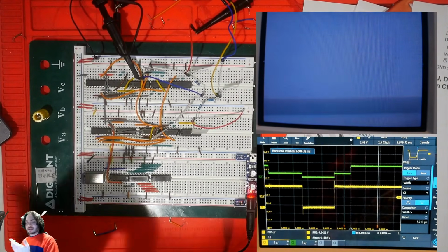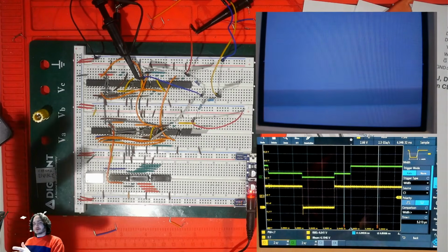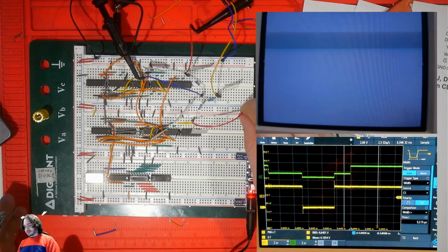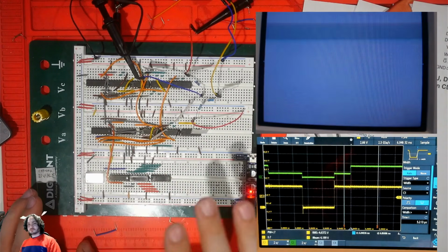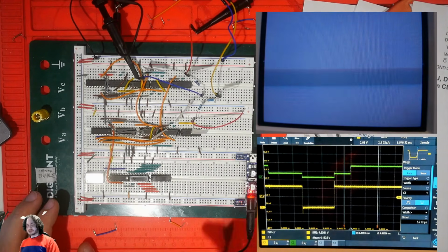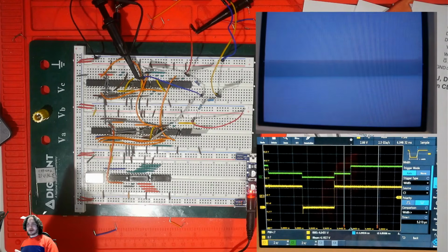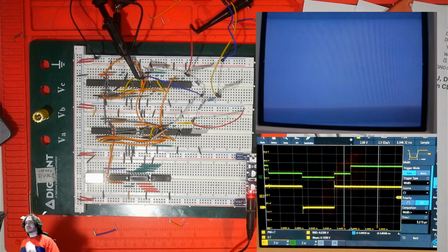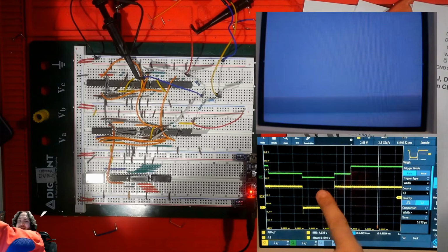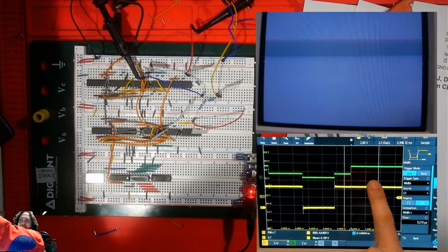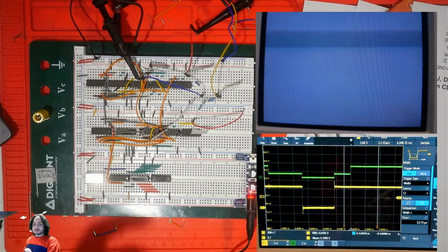In every scan line, we start with H-sync, and then there is the horizontal blanking period. I've currently set the image to be just pure, well, gray right now, depending on the resistors, but a pure, bright image signal is going out during image enable. And you can see there's a little bit of a shelf here going from H-sync to image. And this in between is where we're going to stick something called the color burst.